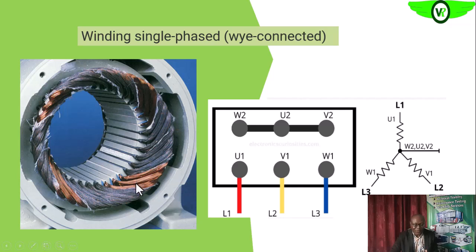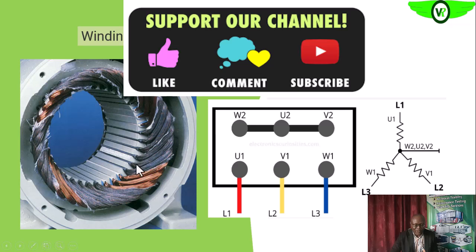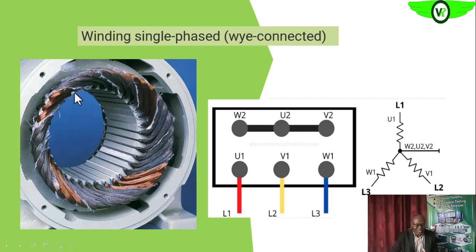These three sets of coils are untouched, while these ones, 1, 2, 3, 4, 5, 6, are burnt. These three, the same thing, they are untouched. This set, burnt. This one, the same thing. This one, burnt. Are you getting it? So there is a clear pattern.